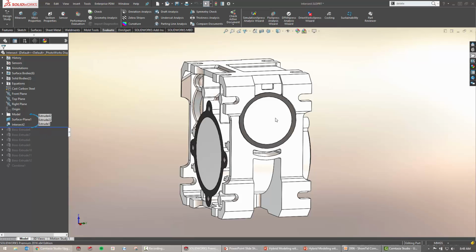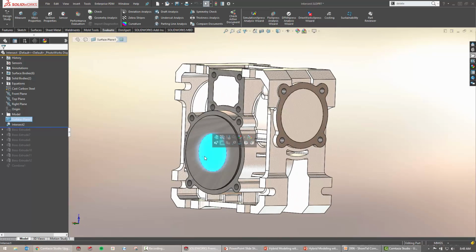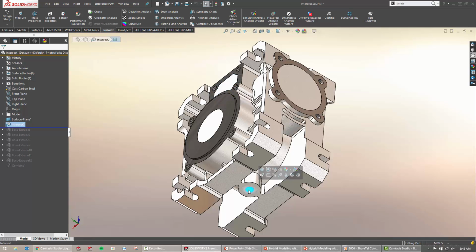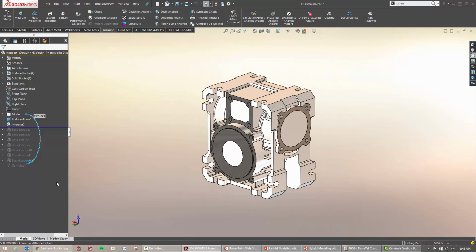Each one of these was an extrude to close off each face one at a time. Okay, and then at the end you create a big box around this. You don't merge results, and then you use combine to subtract and create the interior volume. Well, you can see I've got 7 or 8 features in here, and I'm going to be able to do this with 2 features.